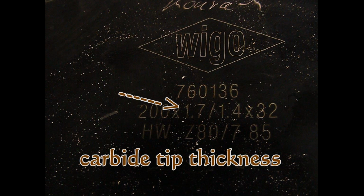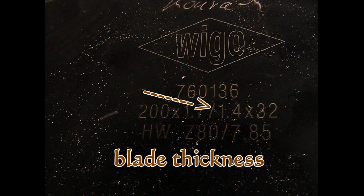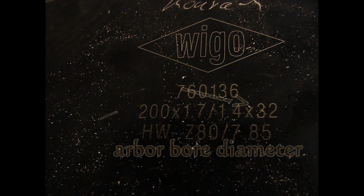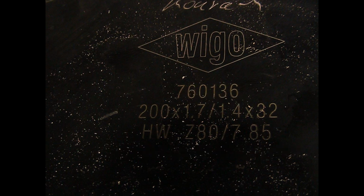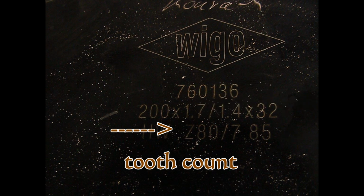And then 1.7 slash 1.4. Now the 1.7 is the width of the tooth, or the carbide portion of the tooth. The 1.4 is the thickness of the blade, and the 32 is the bore diameter. Now the Z80, that is your tooth count.